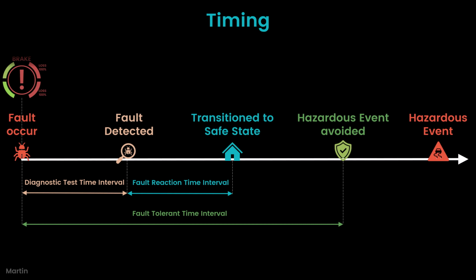In a brake-by-wire system, a fault, such as a loss of braking, can lead to hazardous situations. Upon detecting such a fault, the system must trigger a warning to alert the driver. The driver should then attempt to bring the vehicle to a safe stop.